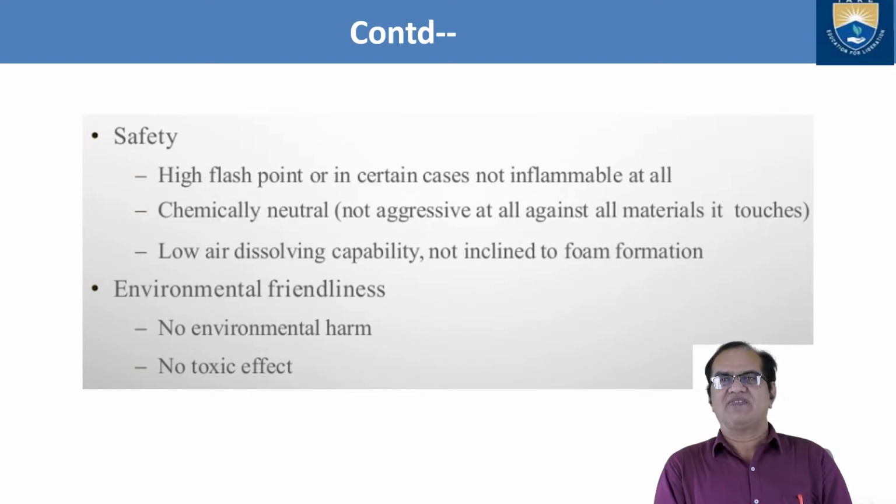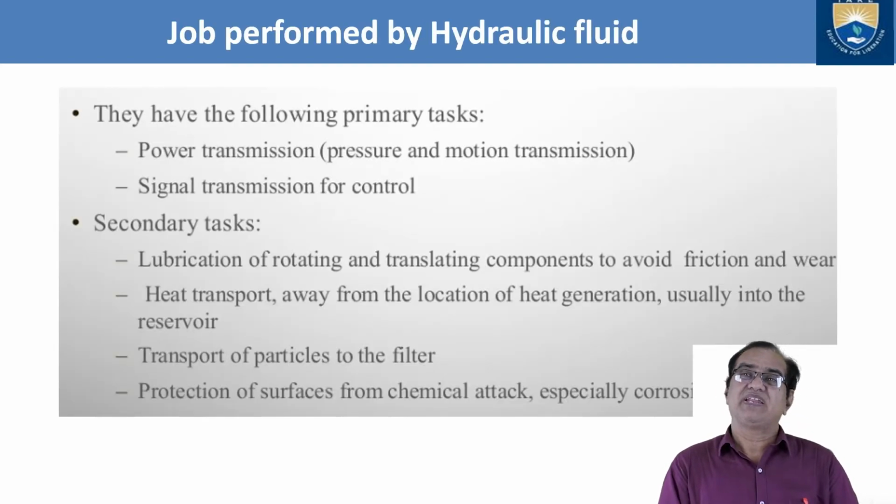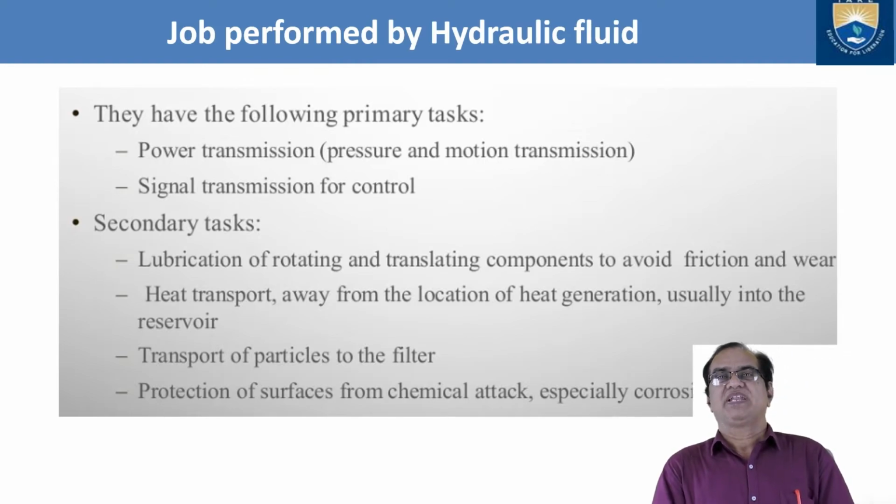Low air dissolving capability, not inclined to foam formation. So it is not even trying to form foam. Environmental friendliness, no environmental harm and no toxic effect. So these properties should be there for any hydraulic system.